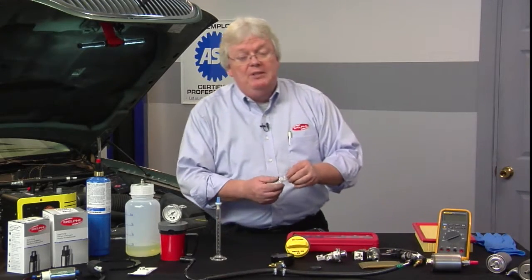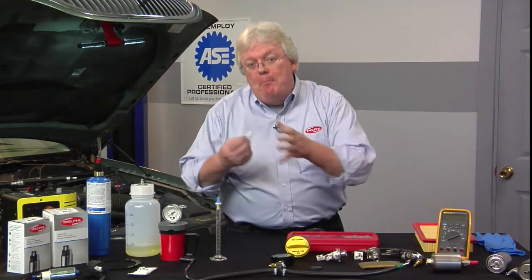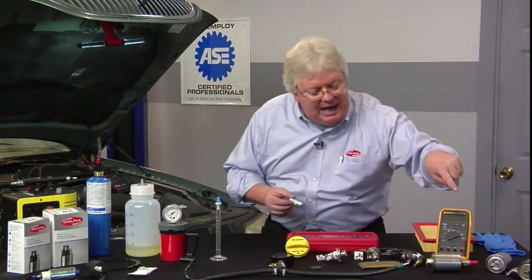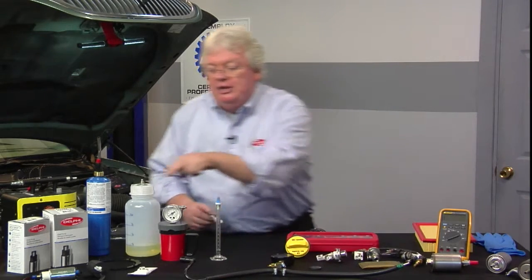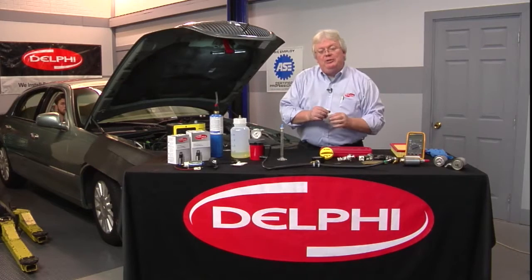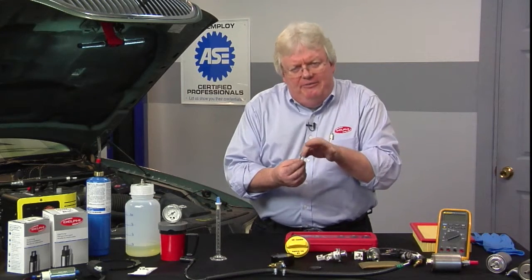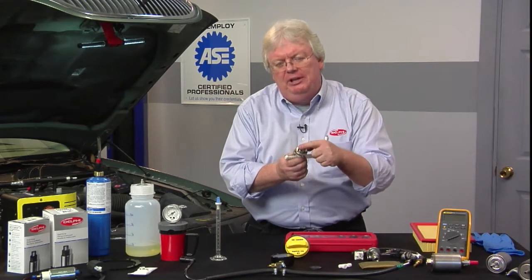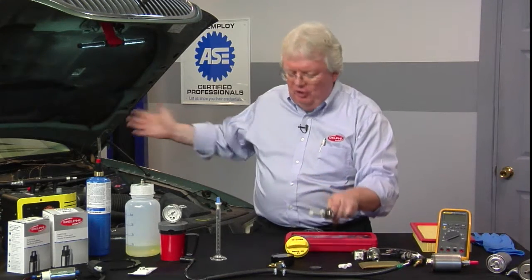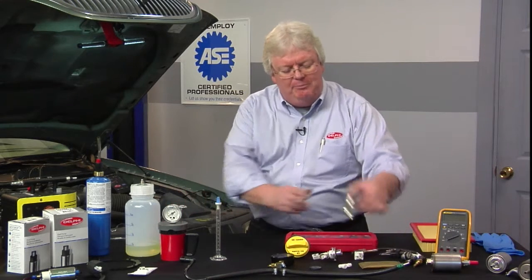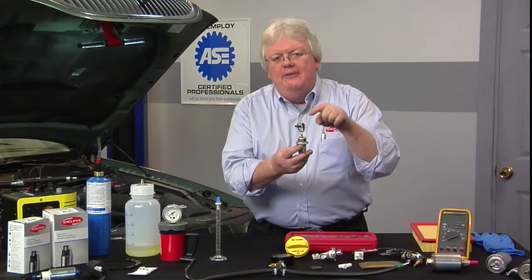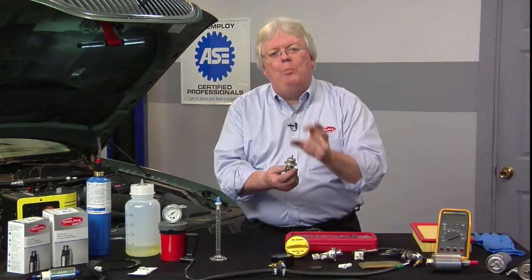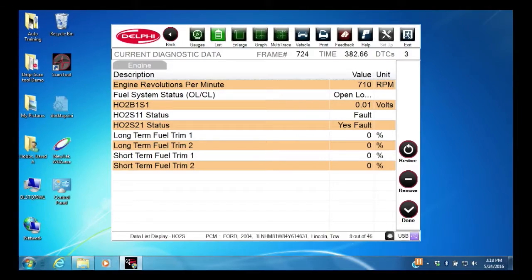In the type of pumps that have the bucket, the modular assemblies, there's something called a jet pump. Nothing to do with the electric side of the system. There's an electric pump there, but on the bottom of that modular assembly, a little jet, the fuel goes through like a valve. Fuel pressure regulator in the modular assembly on the returnless systems, or if this is an old style that has the return system, the vacuum operated fuel pressure regulators on the rail. Anything that could cause the fuel pressure to be low could cause what we're seeing right here.